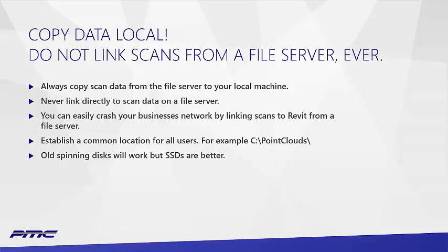Okay. Another thing to consider is that perhaps the hardware you currently have is not appropriate. And that's older spinning hard disks on a laptop. This is becoming less of an issue as more of the solid state drives tend to take over on any newer hardware. But if you still have an old drive that's a spinning disk, seriously consider getting a solid state drive. It likely will double your point cloud performance.